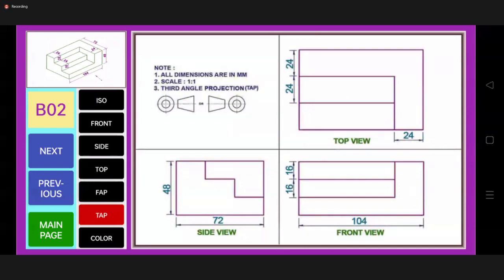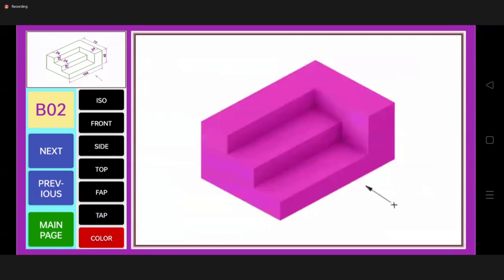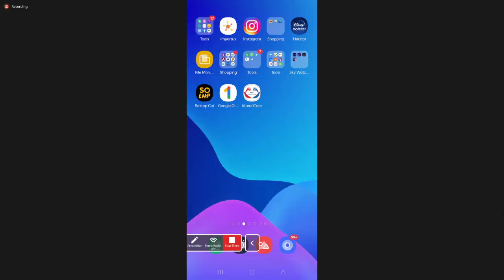You will find the top view is above the XY line, the front view is below the XY line, and the left hand side view is at left, and you can see the symbol there. As I explained in the last lecture, the symbol is the projection of a frustum of a cone. It shows the front view and LHSV. Got it, everyone? Yes, sir. Clear, everyone? Yes, sir.